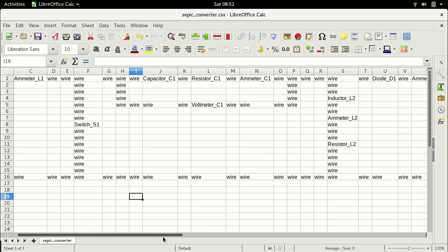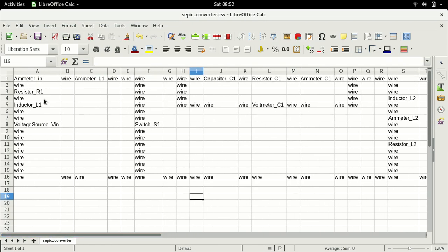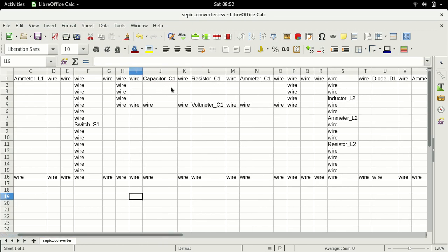So that means this current is expected to be much larger than what it was when we chose a smaller duty ratio. When the switch is turned on, this capacitor discharges through the inductor. We'll look into this a little more, probably in the next lecture.